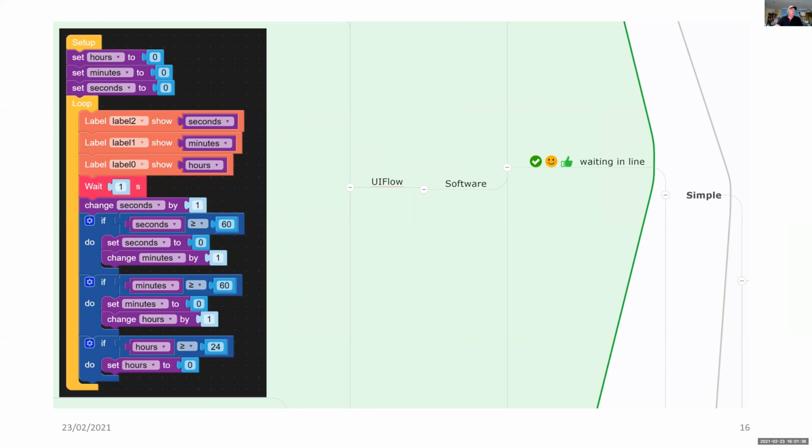The program is going to look like this. Not many steps, but it does have two parts. Right on top, there's the setup, and this is where your program starts. As soon as you power up, it goes into setup, and it only does these steps once. Setup is followed by loop, and loop goes through all of these steps, then just repeats itself.